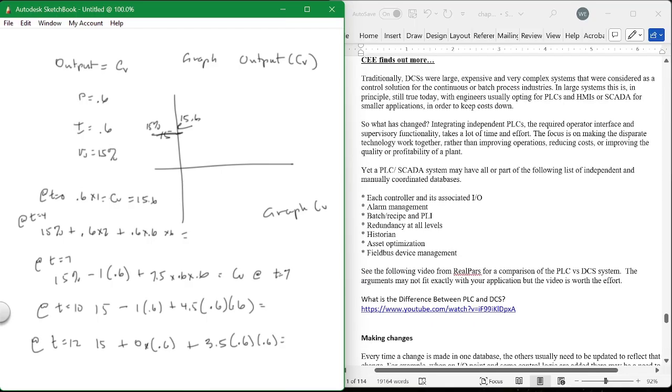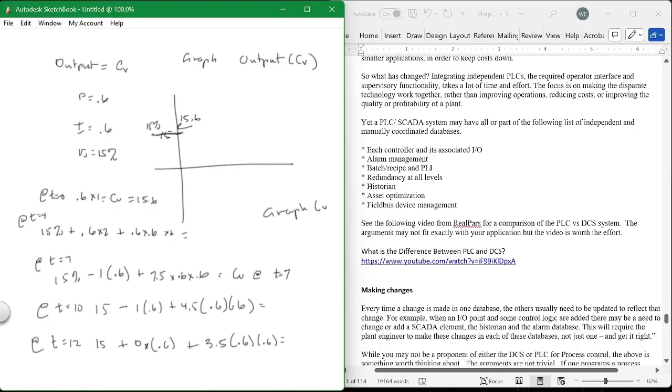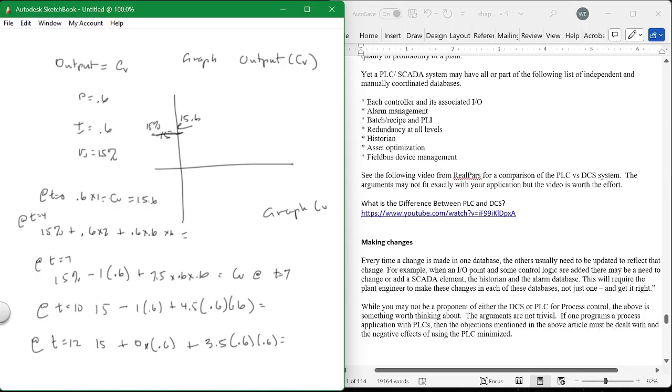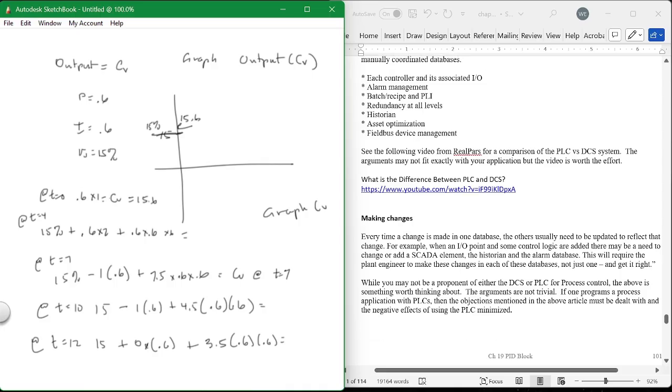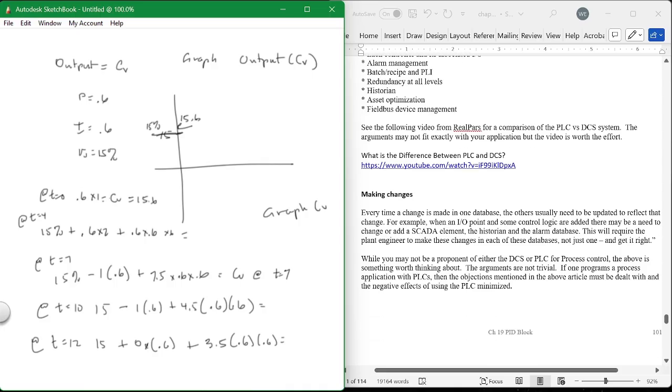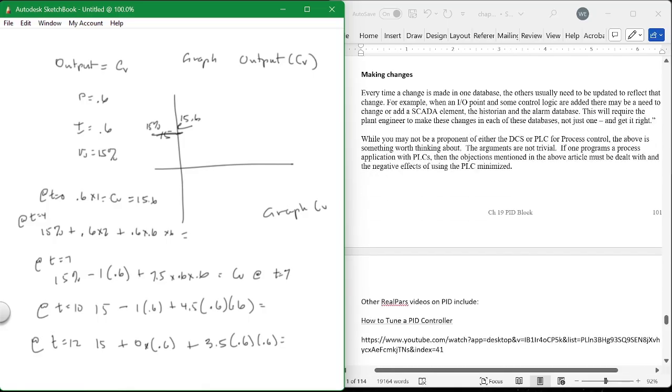And again, to convince somebody that you can do a DCS system after all you've ever programmed has been a PLC system, it's a little bit of a stretch, but you can remind them that PLC systems have FBD, functional block diagram, and many of the DCS systems look very, very similar to FBD. So you can say, yeah, but I programmed an FBD and I understand the differences and all that kind of stuff. But they are not that different, other than the fact that PLC systems tend to be less expensive.